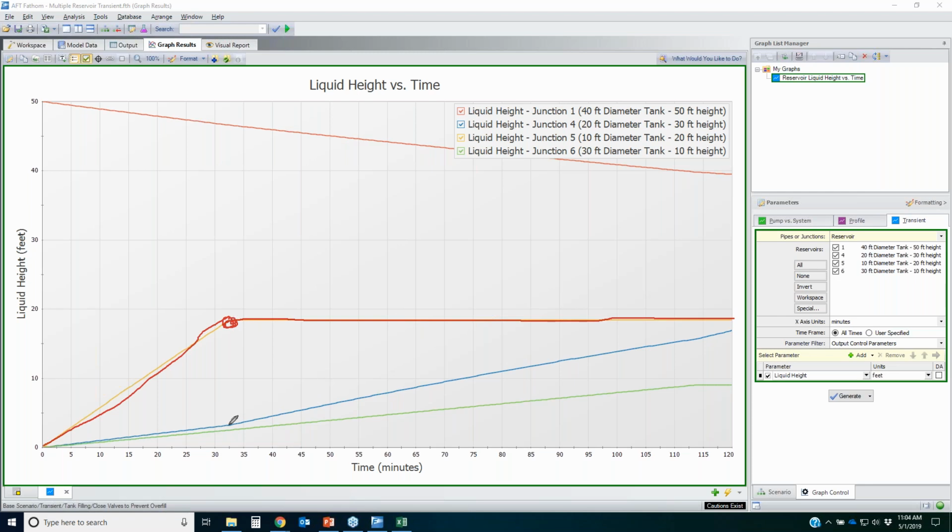What you can see here is a very slight change in the slope for the other tanks here. So when this valve closes, it starts diverting that difference in flow to the other two tanks, and that's why we have a slight change in slope. If we go out later in the simulation, to this point, this is when my second valve closes, and now you can see how there's another change in slope where all the flow is going to the final discharge tank.